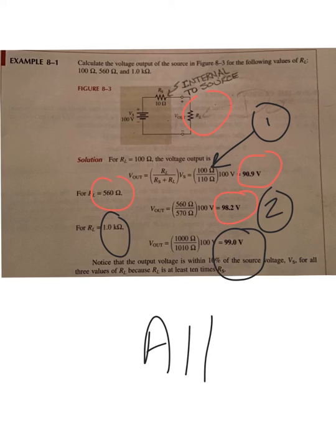Isn't that special? So, what have we learned from this slide? Your battery has internal resistance which drops some voltage as you plug things in. So, if you plugged in a 100 ohm resistor across your power supply in your lab, you might have to dial up a lot higher to get 100 volts delivered to the load.